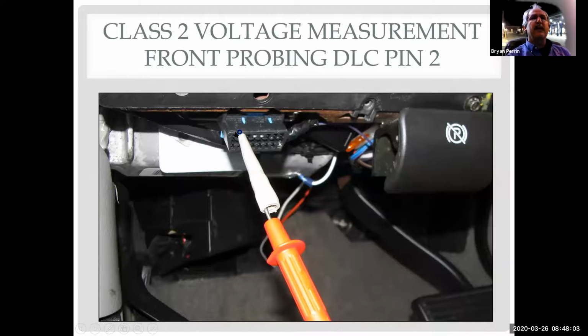Now the other pin I'm hooked into right here is pin 2. So on this particular vehicle, it uses what's called a J1850 protocol, or GM calls it class 2, their in-house name for it. But the actual protocol is J1850 by the Society of Automotive Engineers.